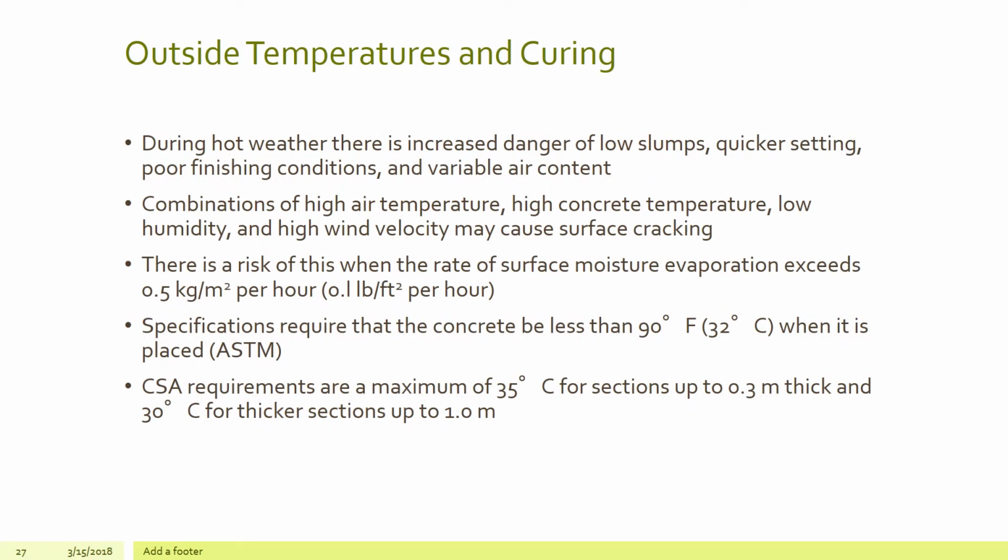Outside temperatures and curing during hot weather: there's an increased danger of low slump, quicker setting, poor finishing conditions, and variable air content. And I mentioned this before. The sun's hitting that, the water's evaporating faster, it's curing quicker, so we really got to keep an eye on that. A combination of high air temperature, high concrete temperature, low humidity, and high wind velocities cause surface cracking.